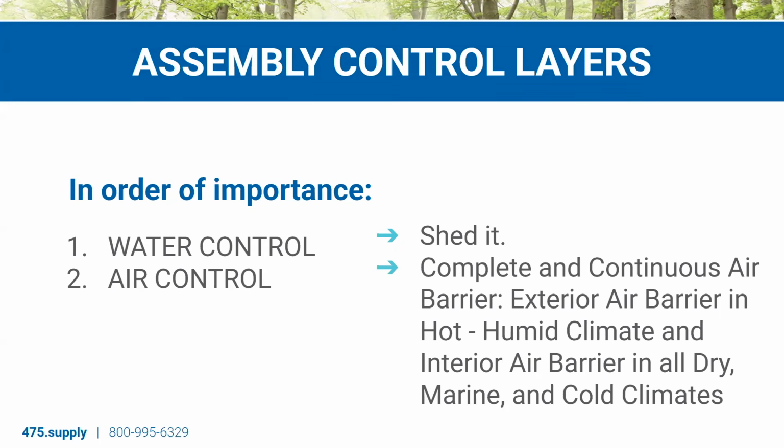And oftentimes the exterior air barrier is vapor permeable and the interior one is vapor variable. That arrangement is really helpful in more northern climates, climate zones 5 and up, where we're mainly drying outwards and we can utilize that interior air barrier as our vapor control layer, i.e. the Intello membrane that's vapor variable.